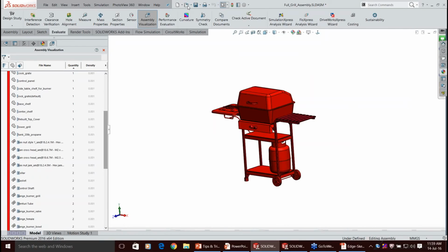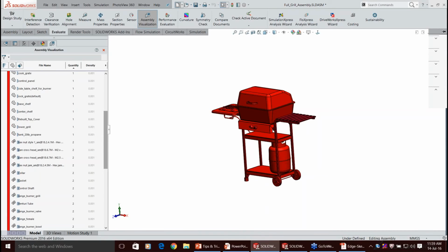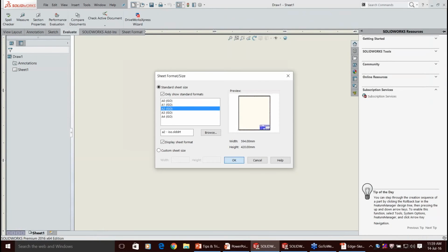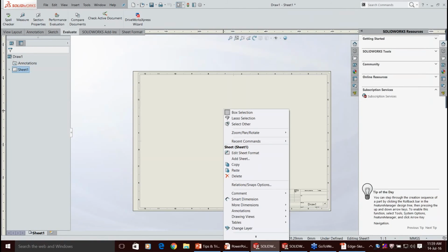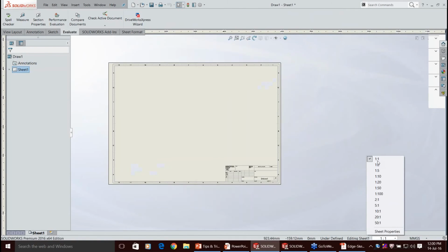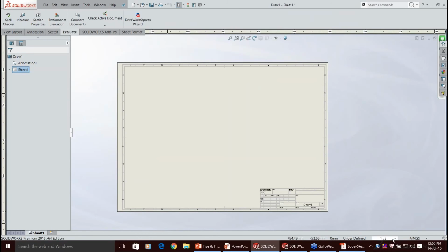So when I just say new drawing, the sheet size. Initially, if I want to change the scaling, we need to right click, go to properties, and then change the scaling, right? But here, now we have it right here. So whatever components or parts, if you want to change the sheet scaling size, everything can be done from right here. You need not go there.